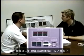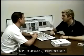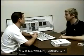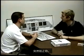What if the alternate brakes won't stop the aircraft? Well, if that doesn't, you're going to have to hope that the parking brake's going to work. So you reach down, turn the parking brake on, and that's going to stop you pretty abruptly.